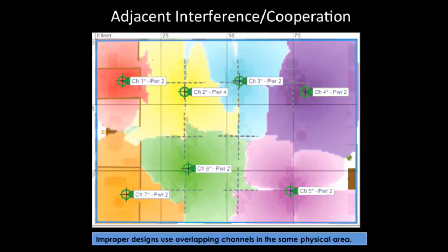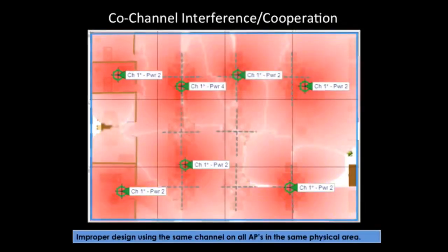So here's a picture, again, showing the different access points transmitting. At first glance, it looks nice. We see 7 pretty colors, the same colors that were used twice. The problem here is we've done a 2.4 gigahertz based design. You'll see this a lot. I do a lot of traveling, and I see this in hotels quite a bit. They decide to use all channels in the 2.4 band. So you get channels stepping on top of each other. So this picture, color-wise, looks good. We have adjacent channel interference in this scenario, which reduces the available capacity that we have for our network. It creates frustration, so you might see guests of that hotel provide negative feedback or choose not to stay in that hotel again. Co-channel interference.